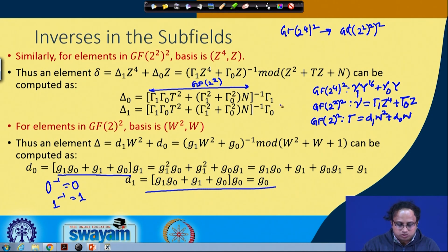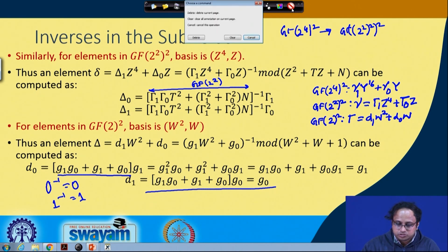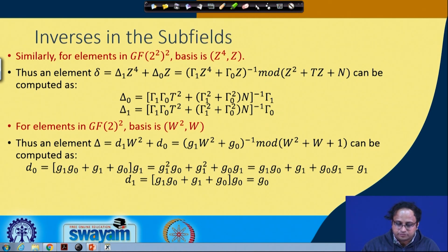And you can also observe that this also means that the squaring in this field will also be equally easy. Okay. So, the squaring and the inversion both in the normal basis in the lowest field is actually free, unlike your polynomial basis where you probably need some XOR gates. So, therefore, that is an incentive for going into the normal basis.